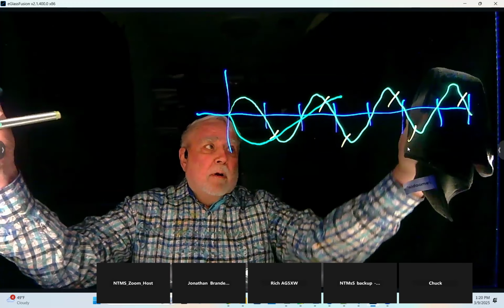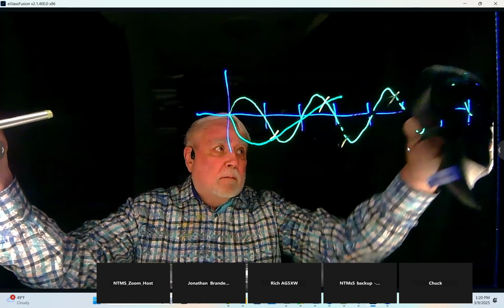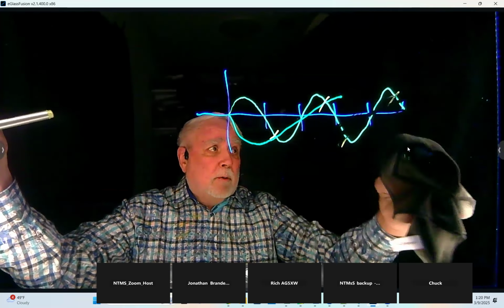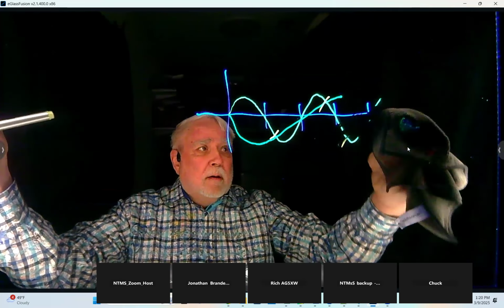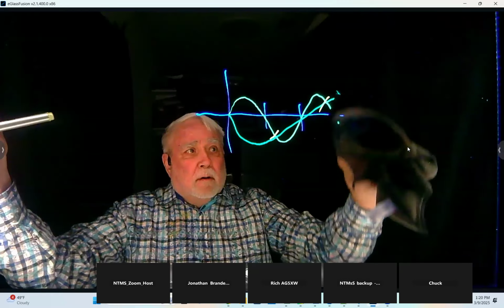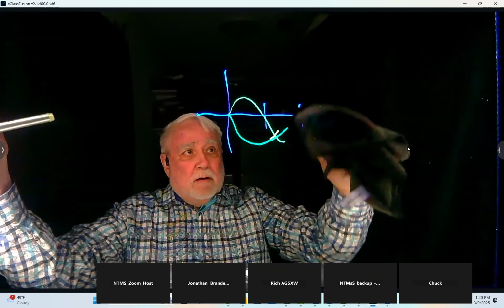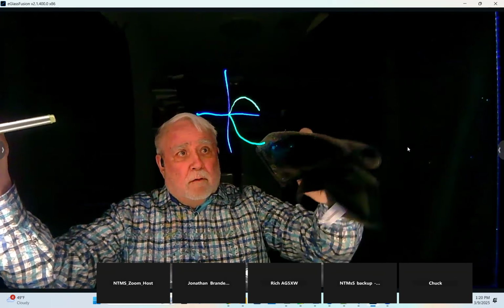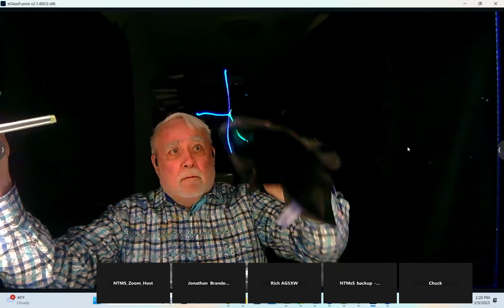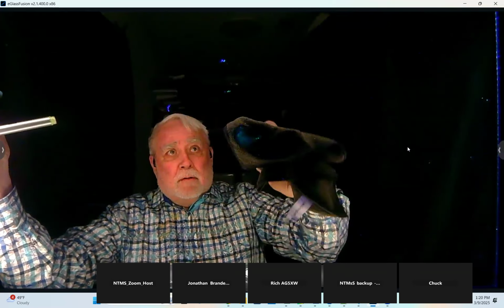So we know from our experience so far that you have to sample at least 2 times the frequency, or you can say 2 times the bandwidth where there is a discrete signal in that bandwidth.